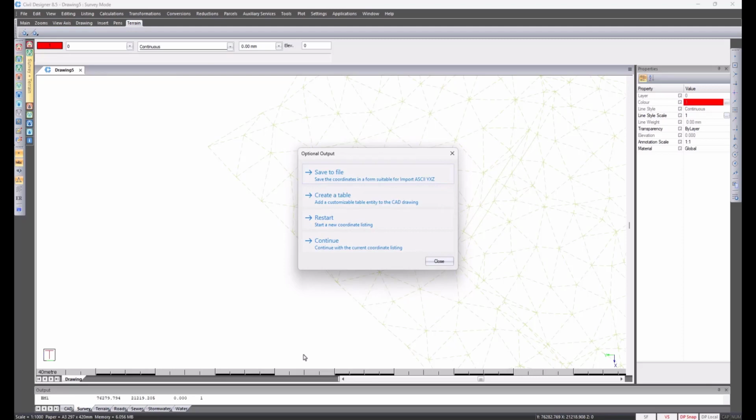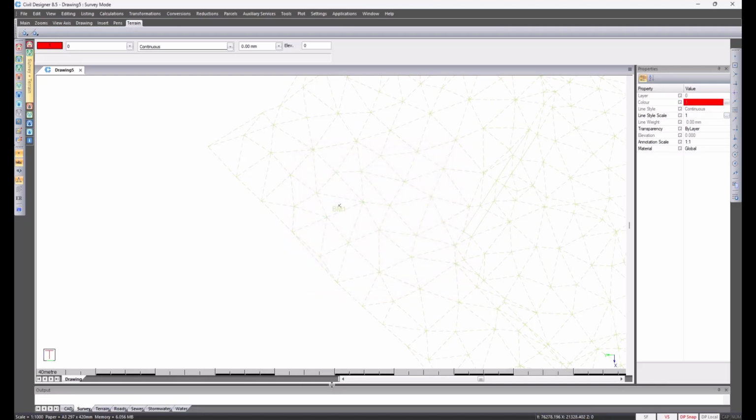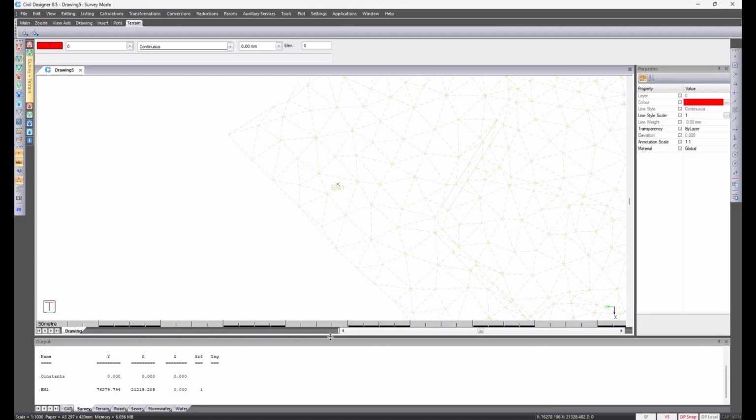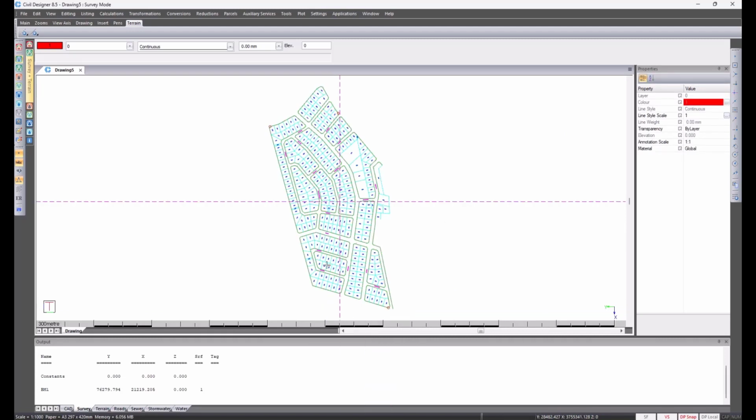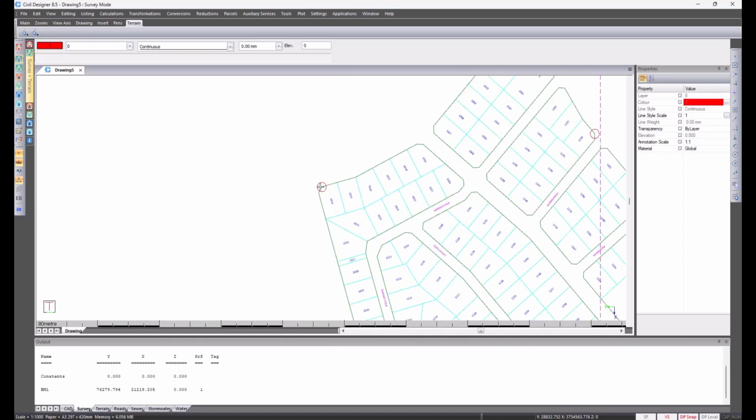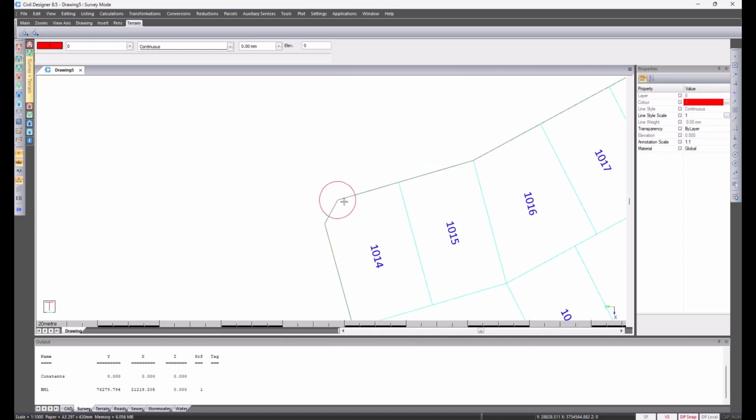Looking at the additional options, you can go and specify a particular output. I'm going to close it. We're done with it for now. If I then go and move my output bar at the bottom, you can see BM, benchmark number 1's coordinates, which we'll utilize shortly. Pressing ZA again, I'm going to select what we've got in the drawing, and then again press zoom selected, escape. Zoom into our benchmark number 1 and get the coordinates of our 3 benchmarks.